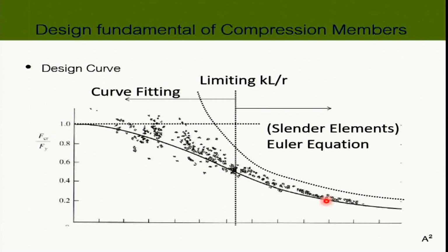It sounds good in one way because we don't have damage on our structure. But it also means that you have a very slender structure that cannot carry as much load as you would want. Okay? So you can see the stress is coming down here because we have the slenderness ratio very, very big. The more it goes on, the less the stress that it can carry.